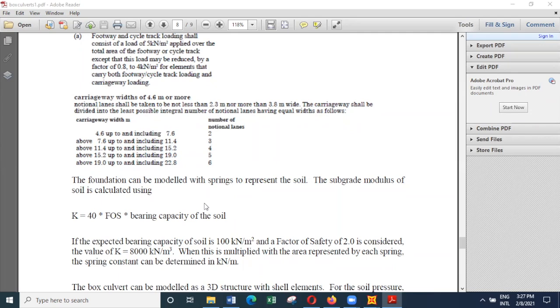So how do you actually apply a soil spring? And as you have seen with horizontal springs, for the vertical springs the equation is simple, because this vertical stress corresponds to a settlement of about 1 inch or 25 millimeters.